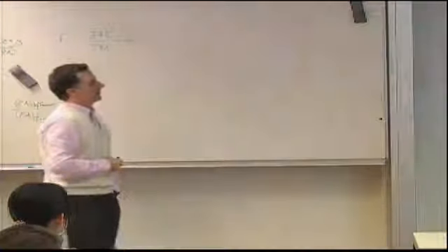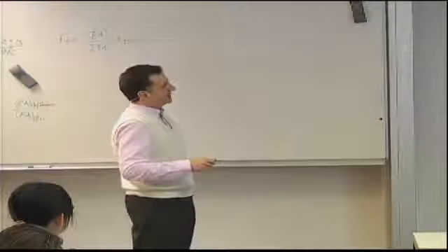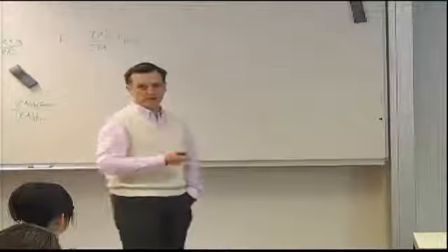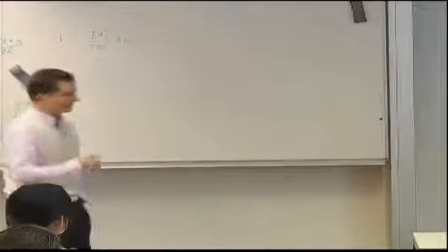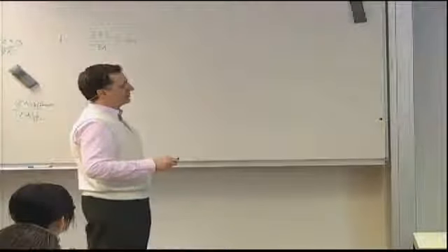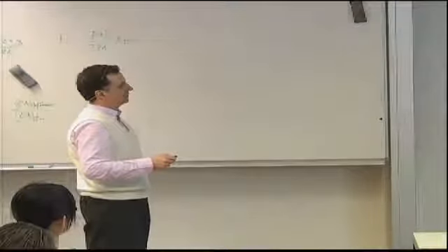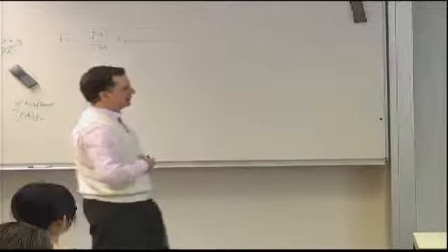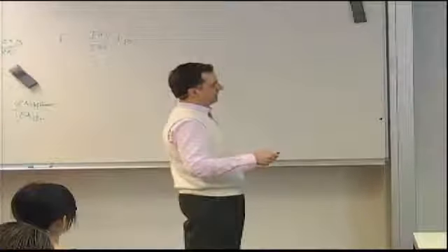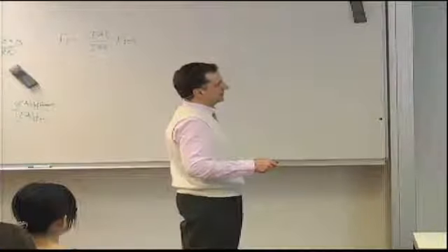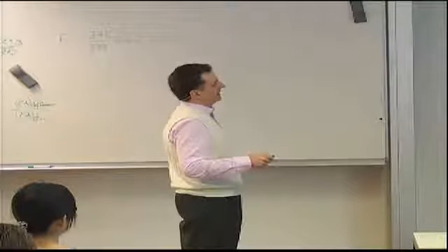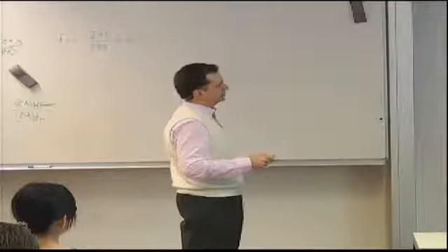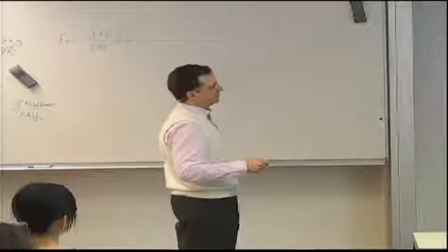So from equation number 3, that's the easiest one because N0 and D11 are non-zero. We want a solution for a non-zero N0, which means C3 equals 0. As soon as C3 equals 0, I can come to this equation, and then C0 is 0. So those two are out. I skip equation 2 for a second, and I go to equation 4, and I impose my C3 equals 0 condition. So I'm left with C2 times this quantity would have to equal 0.